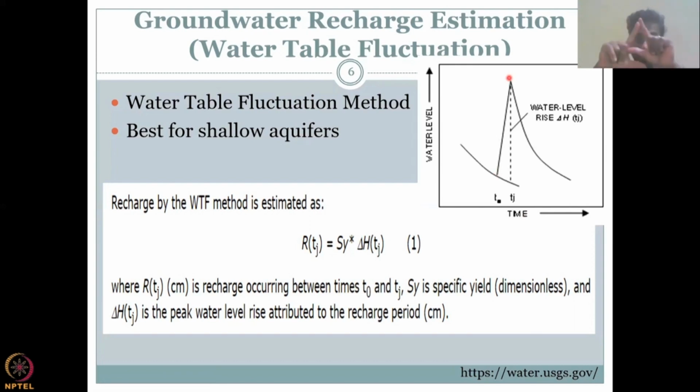See the symbol del? It's like a triangle. That means change. The change in head, hydraulic head or water level, because of recharge during a short time period is called del H. And in that time period, the water is raised to here. It is del H, which is nothing but this minus this one. Okay. And you just multiply by the specific yield, you get the recharge, because the specific yield is a function of the liquid and the rock material.